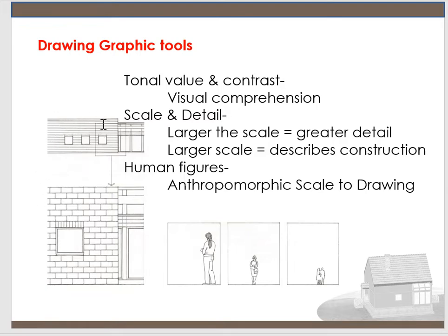If you add so much detail in the smaller drawings, they start to blur when you reproduce them, and they just blend together. So make sure you're using details according to the correct scale of your drawings. In our class, we're going to do 1/4 inch drawings and 1/2 inch. The 1/2 inch drawings will have far more detail than the 1/4 inch.